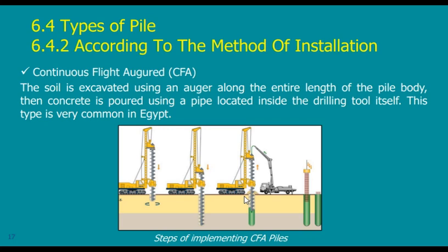But what is the difference? So far I don't have any reinforcement, I just have concrete. In this case I will have to bring my cage and try to insert it inside. Very, very difficult. And if you are a professional contractor and you are following exactly everything and you have the best equipment, you will manage to push this, but at least 2 meters at the bottom are impossible for you.